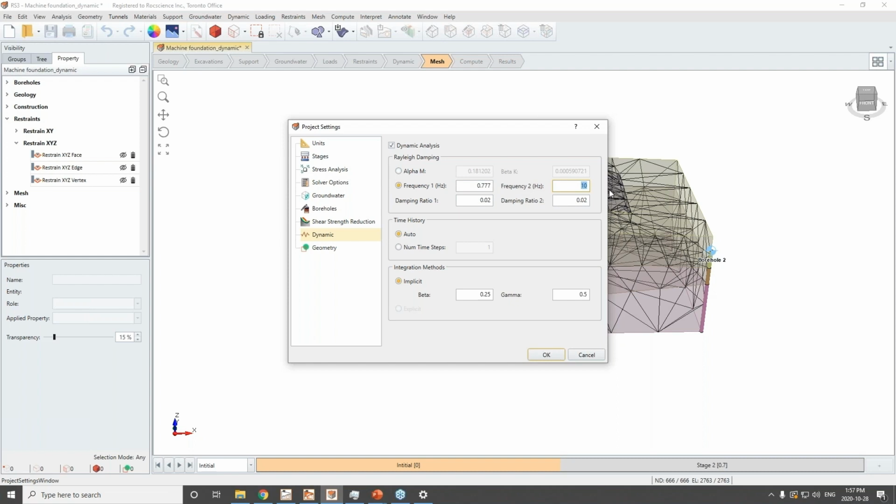So in order to get the second frequency, Hudson, in one of his papers, suggests that the second frequency is the closest odd number of the ratio between the motion frequency, in this case 5, and the first frequency of the model, in this case 0.77, multiplied by the first frequency.